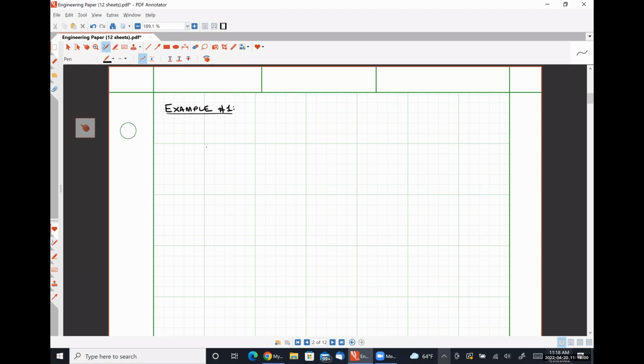So we have the following circuit, and I'm just going to be strictly in the frequency domain here. So we have a 24 angle 60 degrees volts source connected to a 4 ohm resistor, which is in turn connected to a J6 ohm impedance inductor.